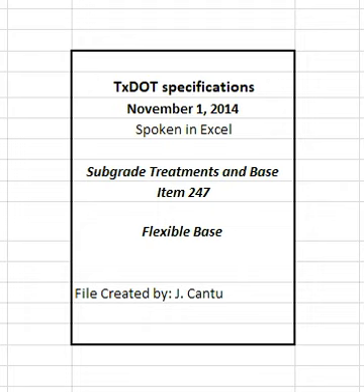6.3 Flexible base, stockpile delivery. Payment will be made for the type and grade specified. For cubic yard measurement, in vehicle or in stockpile will be specified. The unit price bid will not include processing at the roadway.